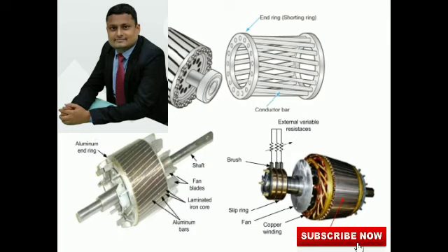So rotor bar design. Rotor bar current IB equals 6 into IS into TPH by SR into KWS into cos phi. So IB equals 6 into 17.5 into 54 into 24 by 2 into 3, divided by 65, into 0.955 into 0.85. You can calculate and tell me what will be the answer. So IB will be 283 ampere.